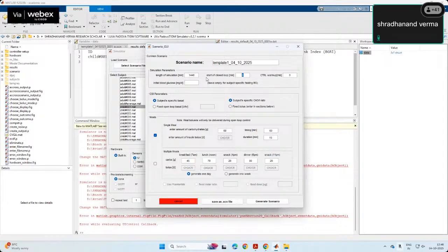That's why this time should be more than the total simulation time. By default it is 1440; it should be more than this. So we are using 2000. Any value more than 1440, 2000, 1500, any value we can put. So here we can write open loop simulation.